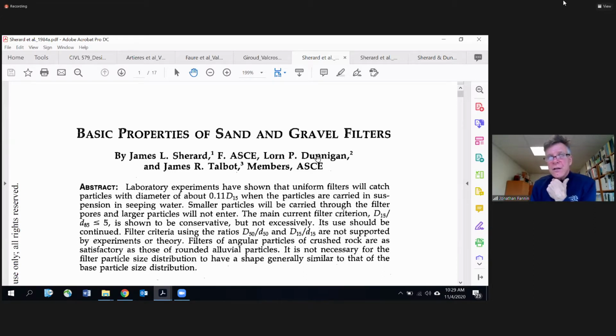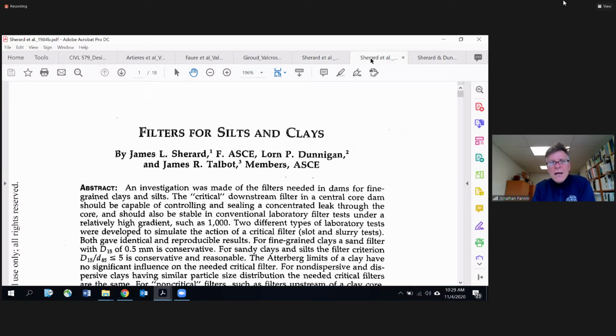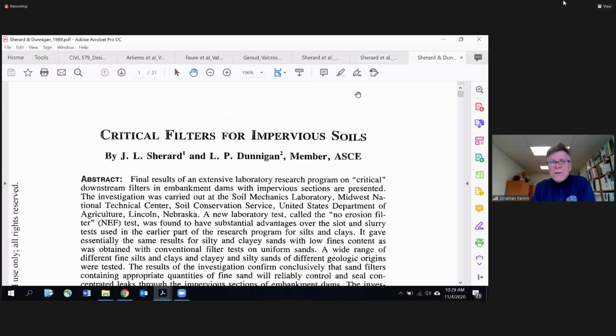I noticed that Lauren Dunnigan was teaching a webinar for, I think it was either the USSD, the US Society on Dams, or American Society of Dam Safety Officials. But I noticed he was teaching a webinar about a year ago on filter design. His collaboration with Sherrard and Talbot, but the long-standing Dunnigan and Sherrard collaboration really formalized the building blocks of modern design practice for filters, granular filters. So 1984, basic properties, 1984 again in ASCE, filters for silts and clays, and then the third one, the critical filters for impervious soils. That body of work collectively is the cornerstone of modern granular filter design practice in the Americas.